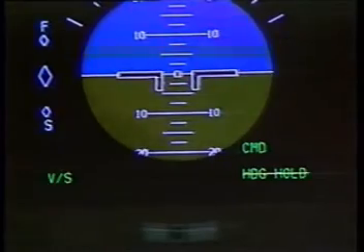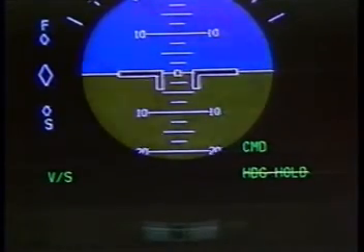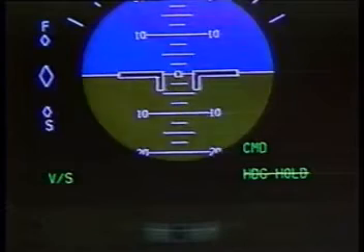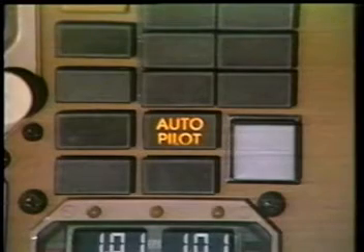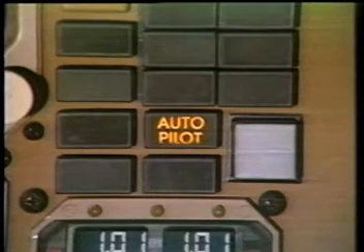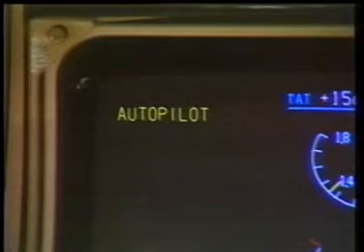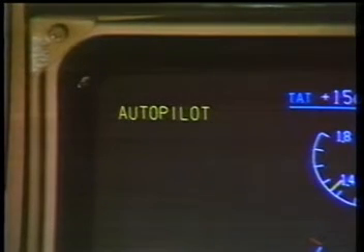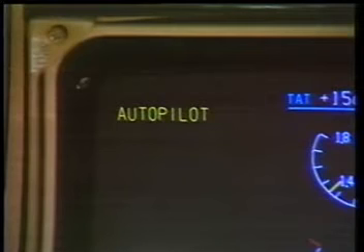On the EADIs, the heading hold display has a segmented yellow line through the display. The amber autopilot light on the P1 panel illuminates. Amber master caution lights illuminate. A yellow autopilot message appears on the upper ICAS, and an aural annunciation is sounded.